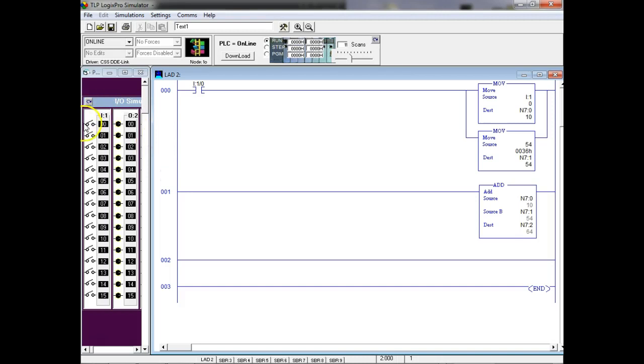So I can come over here and close this, whatever I want to. And then when I hit that switch, what did it do? Well, it's showing me the binary equivalent. This is not decimal over here. And that's what you have to understand. These numbers coming into the PLC are considered to be binary. Right? You understand? But what your RSLogix 500 application is doing is converting it and displaying it in decimal form for us, which is nice, right?